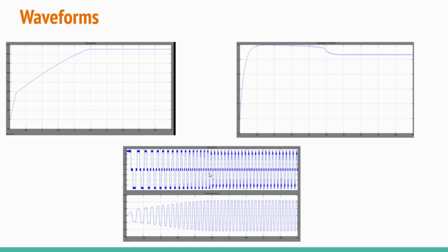By using the synchronous SEPIC DC to DC converter, we get a constant DC output voltage, and that is the input to the DC motor through the inverter. So from the BLDC motor, we get constant speed characteristics, and also constant stator current and electromotive force with respect to time by using the closed loop system.